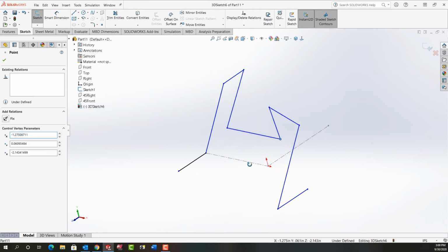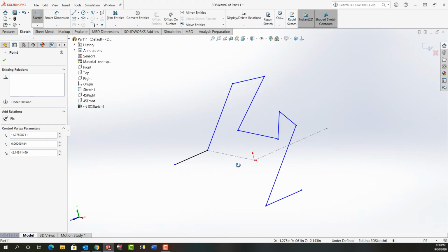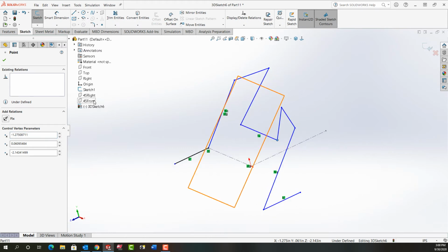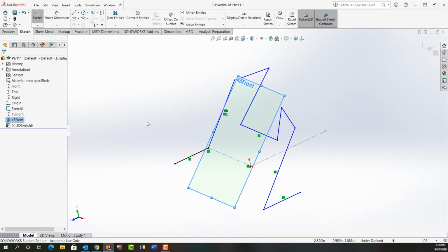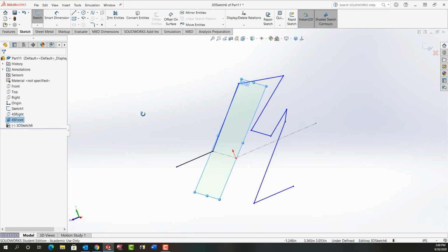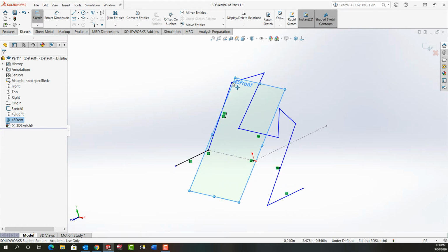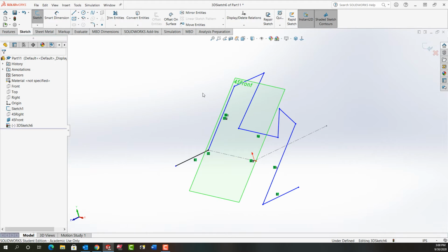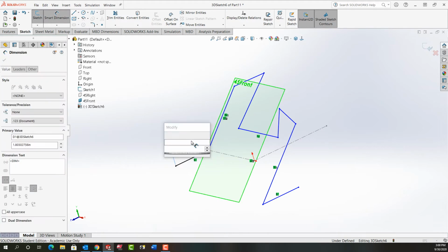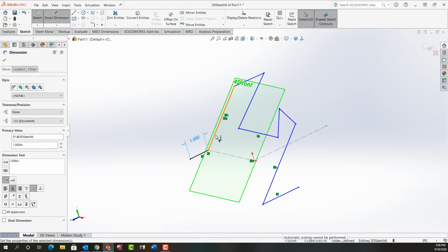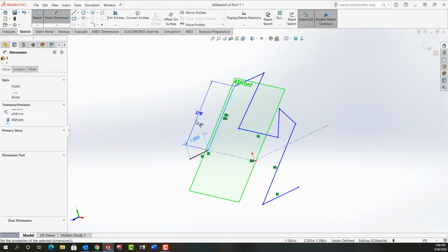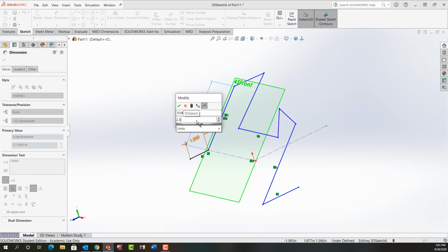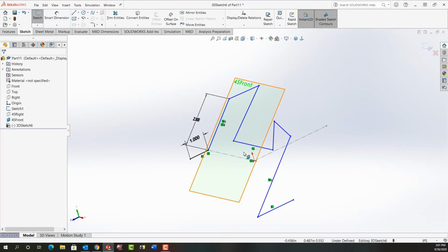For a sketch like this, you may only want to do a few lines and then fix them up. So even though, let's show this plane, it is on that plane. We can see that if we rotate around, we still need it relative. Right? I can swing it all over the place. So if I add the dimension, which I'll now do, fully define this one first with the 1-inch dimension, and I'll dimension this line. It's 2.5 inches. Just going to push escape to stop dimensioning.